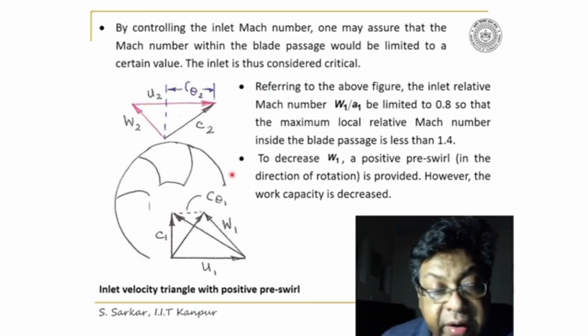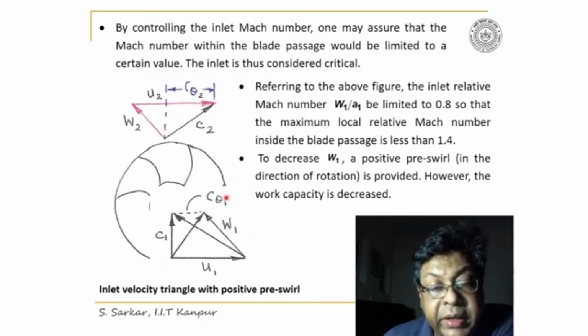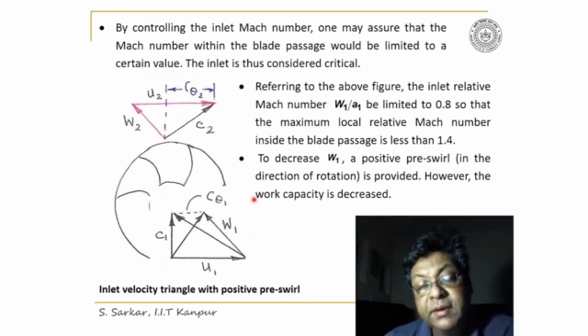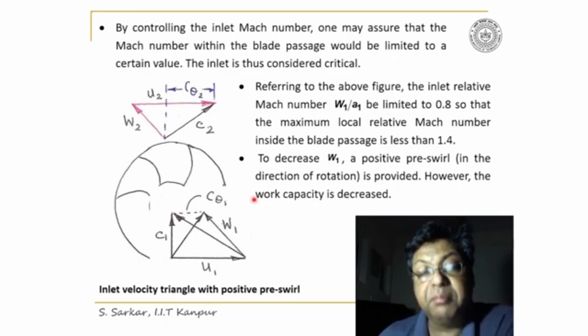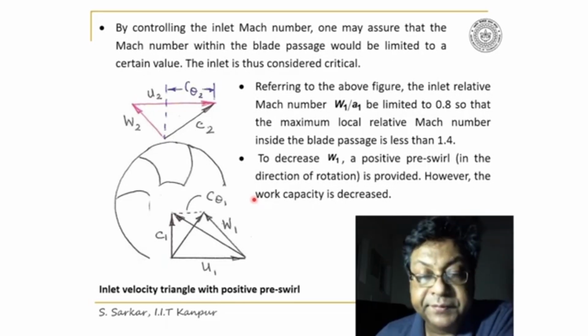I have shown here inlet velocity triangles with and without positive pre-whirl. That means I am telling you how I can control inlet Mach number for a compressor.